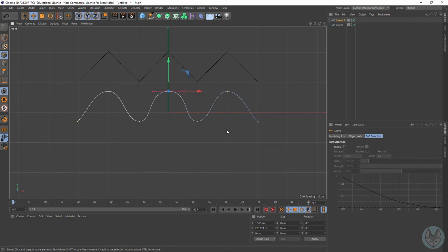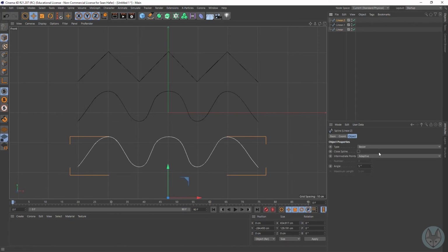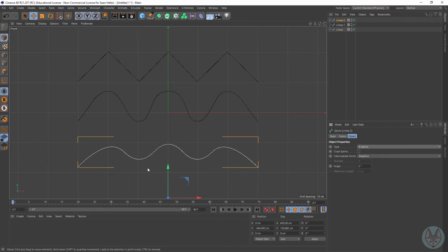So that's how you can do that. So that's a Bezier spline, just like Illustrator. Now if we take this and go to my object tool one more time, Command drag down. Now what we can also use is what's called a B-Spline. If I click on that, come over to my spline type, and I hit B-Spline, now you'll see what's happening.